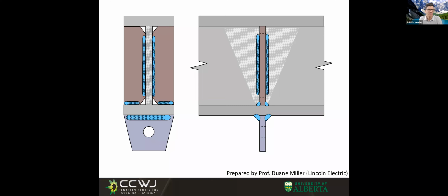But in addition, there is very little load that goes up to this part, because this plate transfers the load to the flange, and if the flange wanted to bend, it is actually transferring it to this other reinforcement plate. And all the load happens kind of in this little triangle here. All this other part might as well not be there.